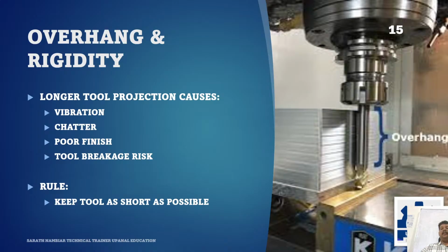Use only enough length, not extra length. If a deep cavity is required, reduce aggression and choose a strategy carefully. Sometimes changing the holder or tool length solves more problems than changing feeds and speeds.